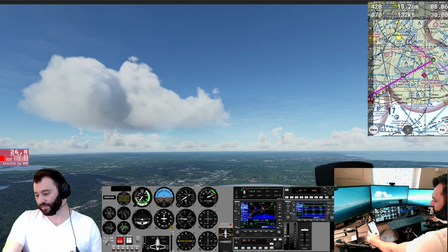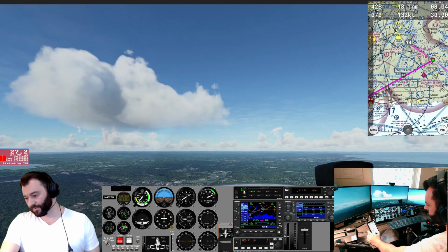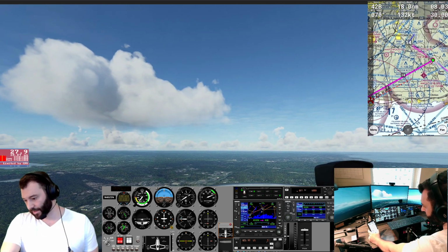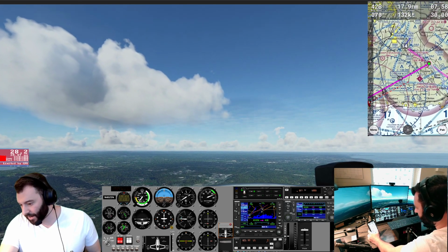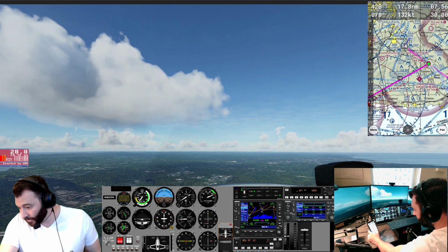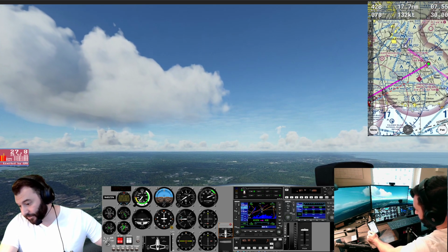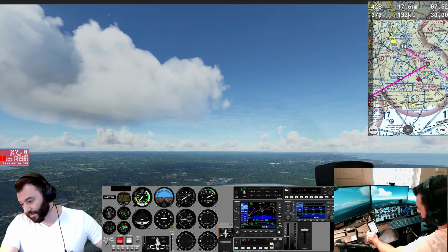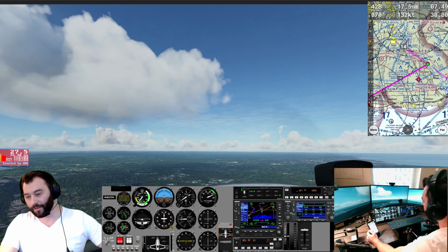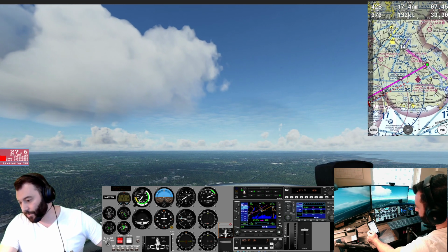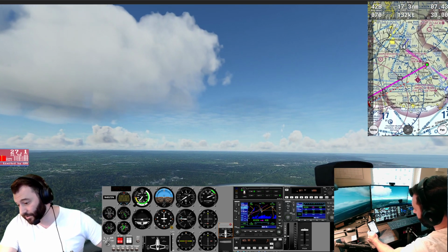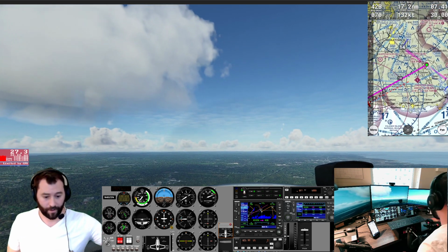Alright. So we don't have to tune up Chester. I'm just going to steer clear of it. I'll stay outside of it within 3 miles or so, just because Goodspeed is right on the back side of it, we don't have enough time to switch from one frequency to the next. Just for the sake of doing the practice, assuming we're on a long flight here and we need to get weather coming into our destination, there's no weather at Goodspeed, but there's weather at Chester, so I'm going to tune up 118.325.